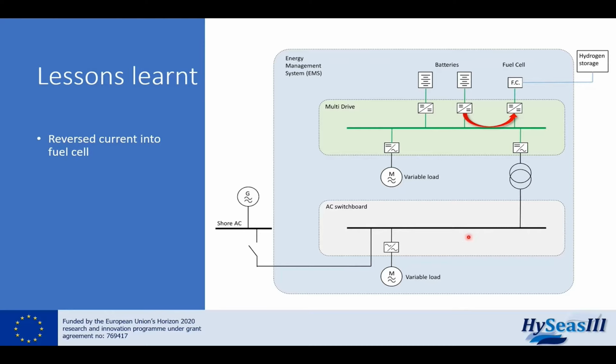We damaged the fuel cell and had to send the unit for repair. It turned out not to be damaged significantly, only a burnt contactor. We saw that including a fuel cell into a large and complex system shows that the fuel cell needs to protect itself from damage, and a diode was included in the circuit to prevent reversed current.